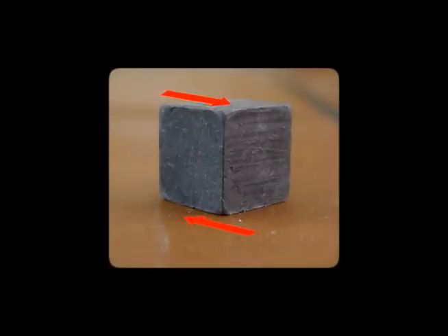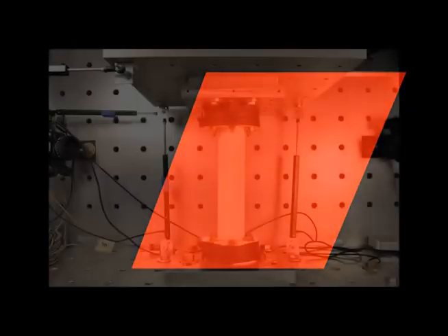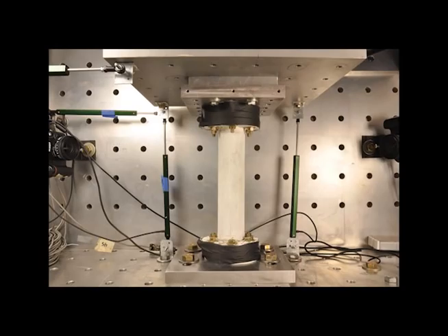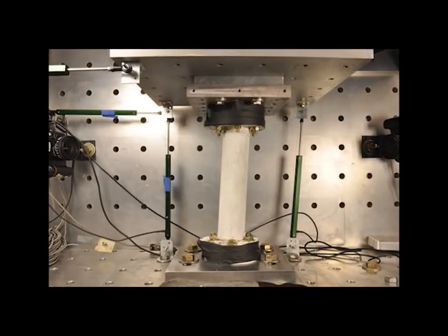Shear stress is a stress which is applied along the surface or plane of a structure. When applied to a square, it causes it to take on the shape of a rhombus. Shear stress is applied to a bridge pier when there is a lateral movement of the top of the pier relative to the bottom of the pier, which is fixed in this case.